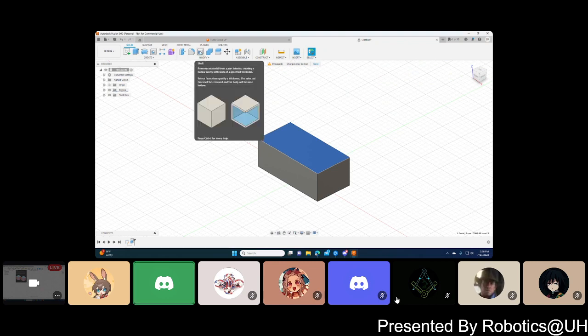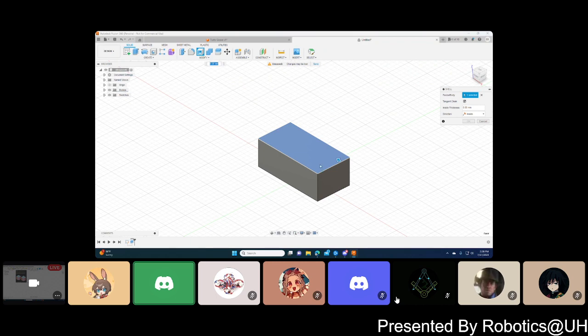So shell, it's what you could use to basically make the object hollow and have walls that are a certain thickness that you specify. So I'm gonna click that. You can click the face you want to have as the open end first and click it, or you can just click shell and then select it. As the direction is inside, you can.